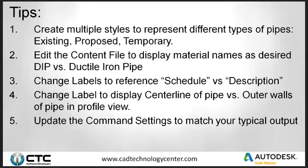Definitely edit the content file to display material names as desired. I just finished talking about that, DIP versus ductile iron pipe, and that's basically combining steps 2 and 3. Change the labels to reference the schedule versus the description, the ID material. Those two combined, you can get your labels to print out what you want. It just takes a little bit of setup within your content editor. Change labels to display center line of pipe versus outer walls in profile view.